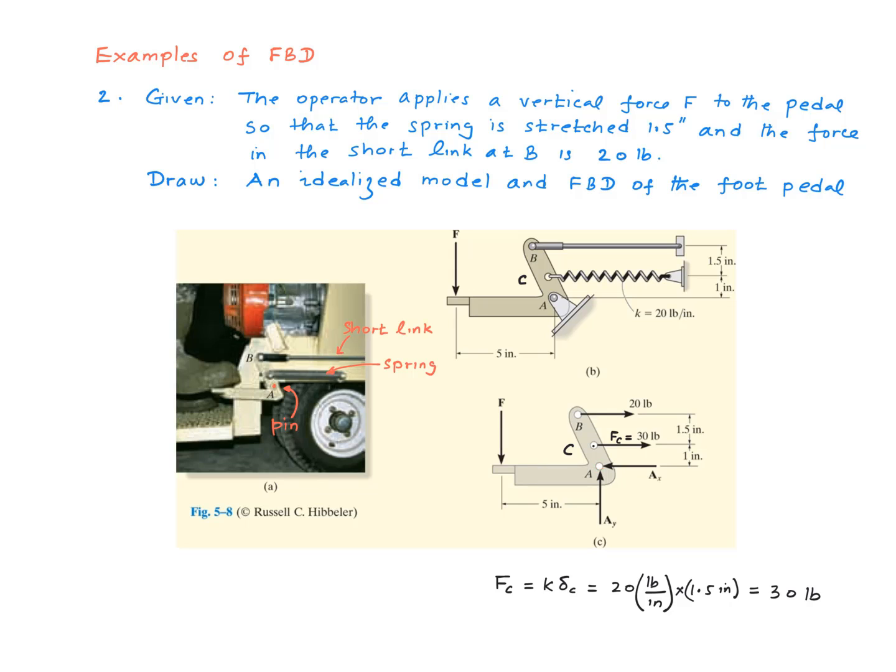Now this is a pin, and therefore there could be two forces at that pin, one in the horizontal direction and one in the vertical direction. Again, you don't know the directions at this point, so you can mark them in any direction you want. Here I have marked the vertical force in the vertically upward direction and the horizontal force in the direction going from right to left.